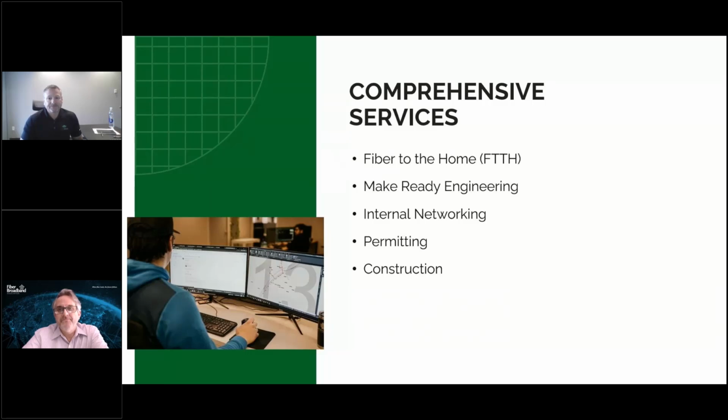Got it. And this one might be a little bit specific, but somebody is asking if you primarily use microducts for interior attic spaces or whether you use free air for the cables. Both. Again, it depends on the structure. I personally like to use the microduct. It goes back to one of the comments about future proofing. If for whatever reason that fiber needs to be replaced, you have a direct pathway.